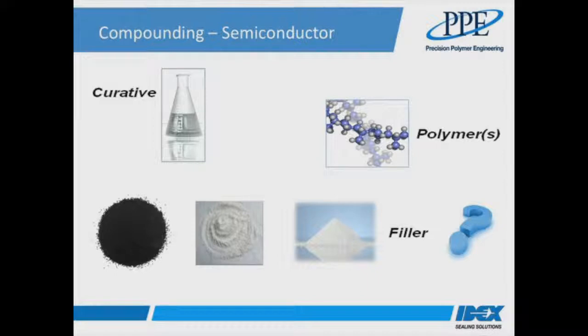Finally, on the subject of fillers, there are also so-called organic reinforcement systems with typical filler types including PTFE and PFA. The natural extension to such fillers are then the dark arts of filler-free systems, where the polymer architecture itself can be described as self-reinforcing. PPE utilizes these types of novel technologies in several elastomers or elastomer grades. These organic filler or filler-free materials can be regarded as the purest, being entirely organic elastomer materials.